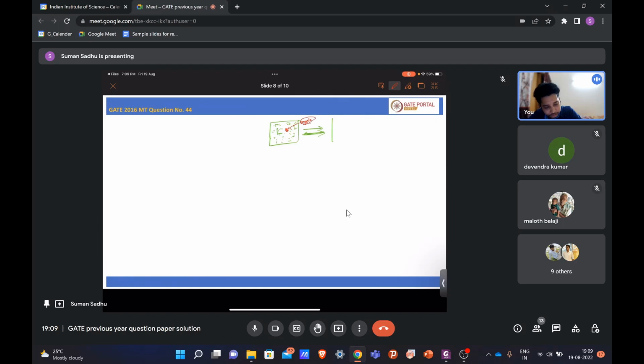This is the short range ordering, but that regular pattern is not stable when you are at T_m or at a temperature greater than T_m. So suddenly this kind of regular arrangement will form, and suddenly it will break apart. That regular cluster is forming and it is breaking again. So those clusters are not stable at the melting temperature or higher than the melting temperature.